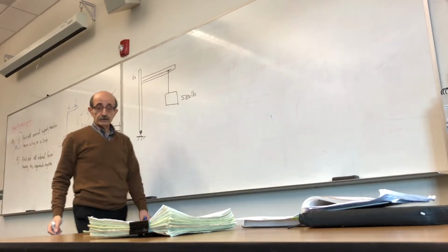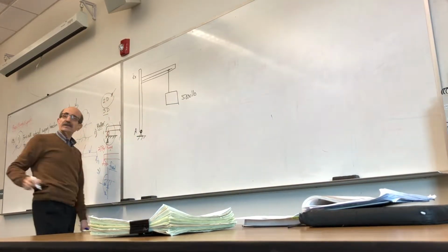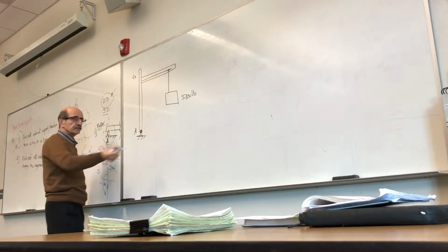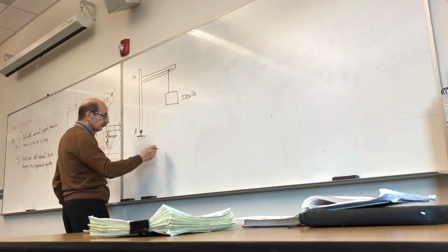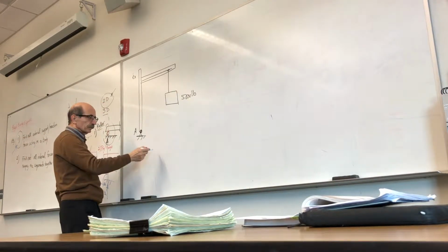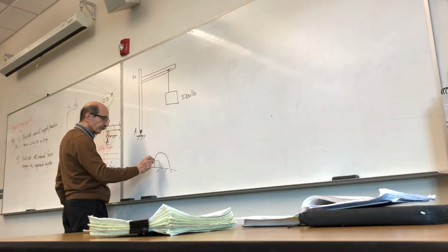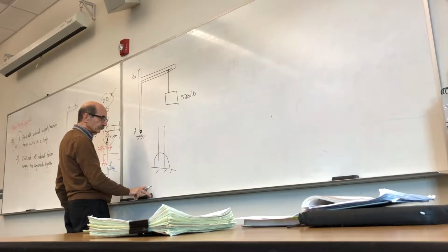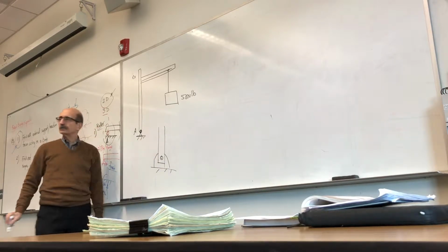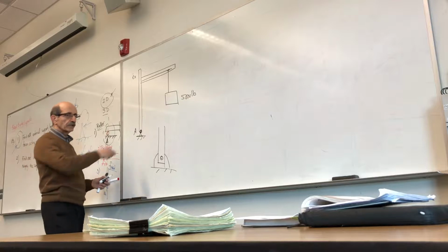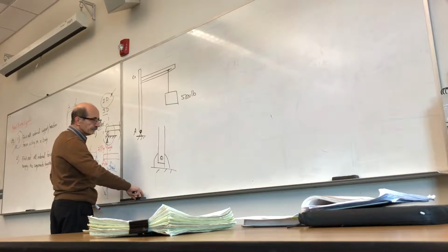This crane structure is supported at the base through a pin, and what that pin, just to give you an idea, you've seen, for instance, in bridges or some columns, how, for instance, the type of support might be something like this. You have a plate. So this column, which is a steel column, simply bolted to this plate. It can rotate, but it cannot move this way or this way. So that's what we have here, okay?